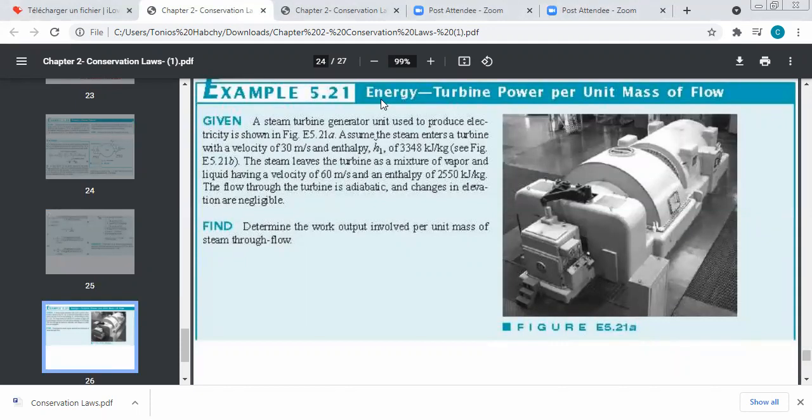So as I told you, in general, if they give you information of the enthalpy directly, you can use it, or you can use thermodynamic tables. So instead of enthalpies, I can provide you with the temperature. If they tell you the temperature of your water, you can then determine its enthalpy, but they should give you temperature and pressure, because for thermodynamic tables you need two properties.